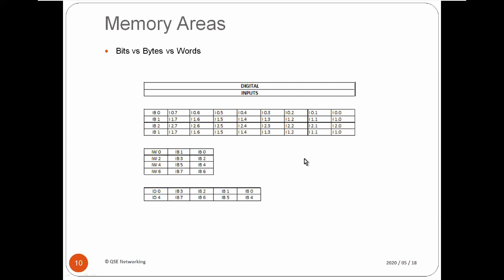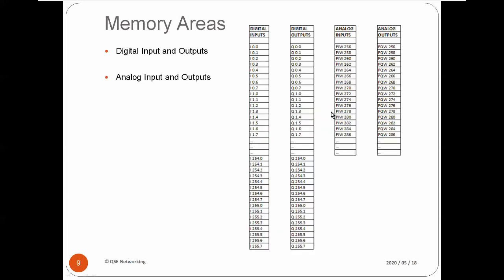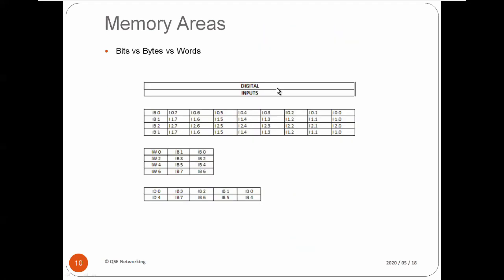It just depends how you want to handle it, but every bit is addressable as an input and output in the same manner. It's very important when you design your own thing that you need to know where the byte starts. I'm just going to go back up one. The input starts at input 0.0 to 255. See, it's always starting at an even number. 0 is even. So just as a matter of principle, always reference your words from the even number. Just keeps life simple.